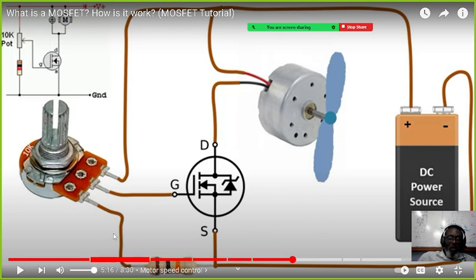What value resistor is this right here? Type of resistor? What value resistor is this? I don't see the color well when I pass it. Brown, black, orange. Brown is a 1. Black would be 0. Orange will be what? Orange is supposed to be 3, isn't it? So it is 3-0. Yeah, 3.